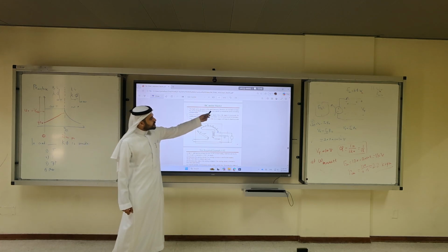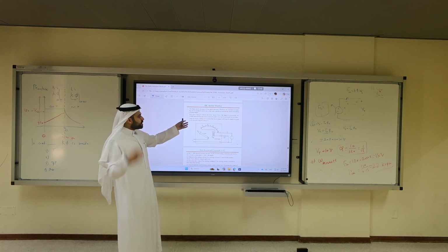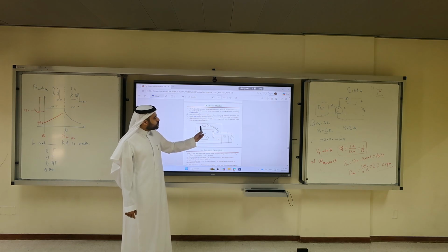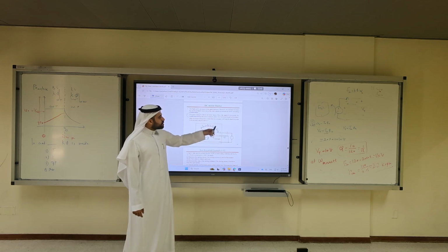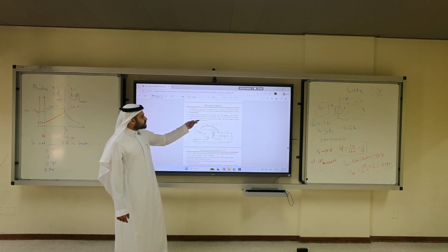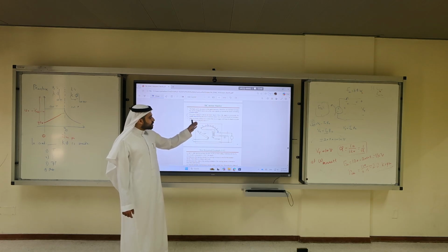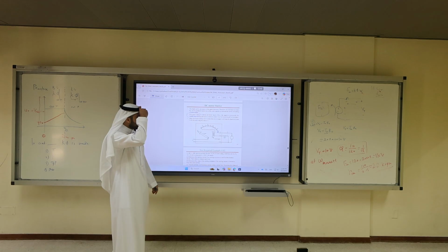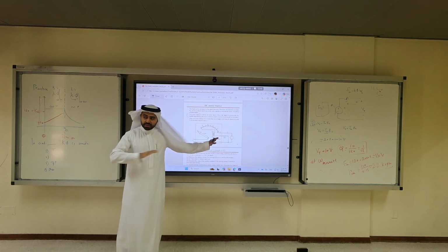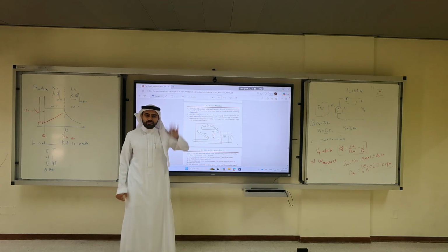So the back EMF increases as the speed increases, and external resistance is added using the 5-point starter. The supply is connected, and the handle starts moving, traveling between point 1 and point 5 until all the additional resistance is removed. Since the field windings are excited, the electromagnet will keep the handle at point 5 until the source is disconnected. So it will maintain point 5 at steady-state operation. This is the 5-point starter.